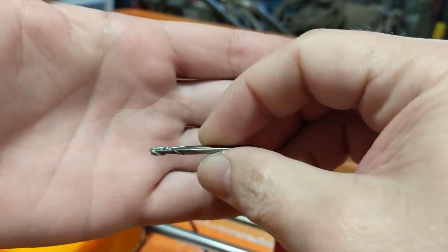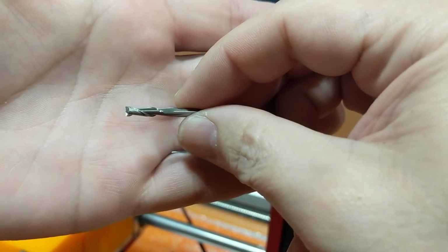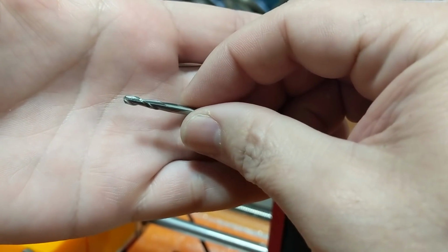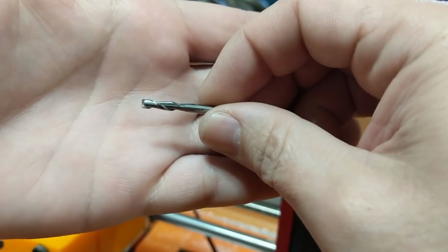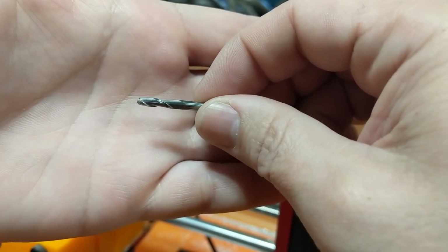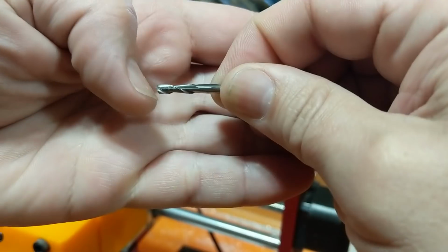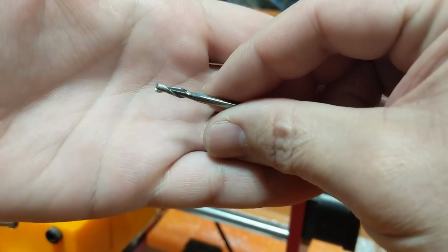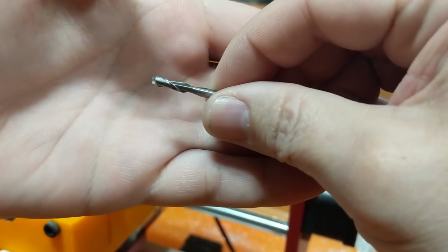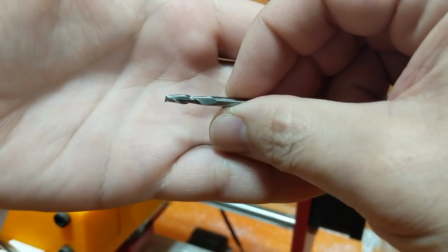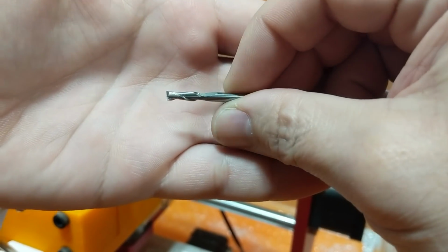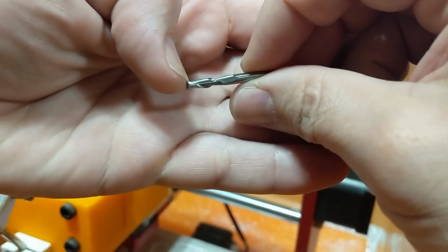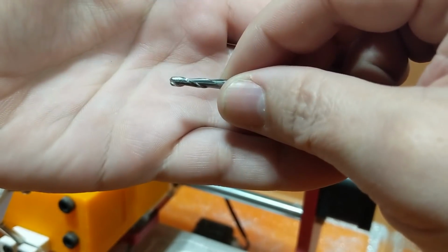Okay, so you guys saw the single fluted bit all clogged up with aluminum. And this is my 2 fluted bit that we started off the video with. And I've chipped it clean the best that I can, but there's still aluminum coating the flutes here. So I can soak this in a bath of lye or some other kind of chemical similar to that and clean off the aluminum. But that's kind of a pain in the butt, and it's just going to get clogged up again really quick.